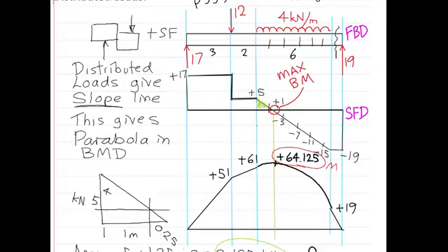Right, well that's about as bad as they get when you have a distributed load. You'll be making a straight line instead of a horizontal line. You make a line on an angle in the shear force diagram, which creates a parabola in the bending moment diagram.